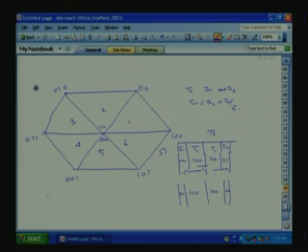So, we have a positive sequence and a negative sequence. This way it will go, and that will ensure minimal switching. This is the first Ts period, and this is the second Ts period. Here we start with 0 0 0, then 1 0 0, then 1 1 0, then 1 1 1.